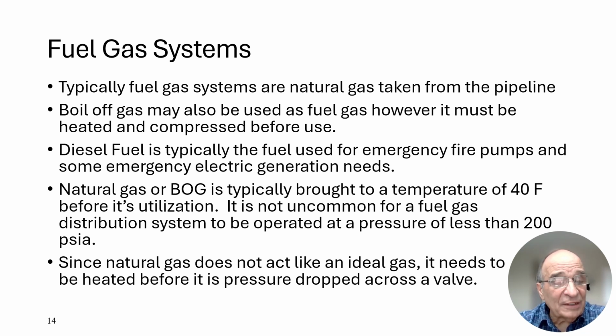It is not dependent on your fuel gas system, because the fuel gas system could be compromised. That could be the actual emergency. Let's say there's a break or a fire in the fuel gas supply line. Well, that would be shut down, and then you would have no fire pumps and no electric generation capability.